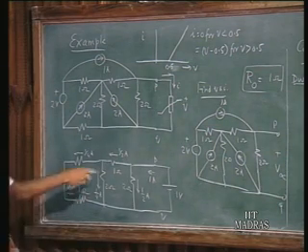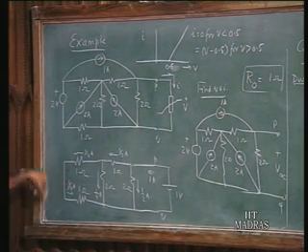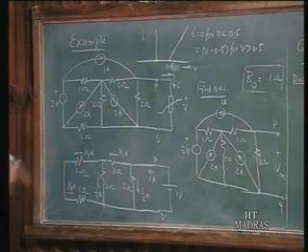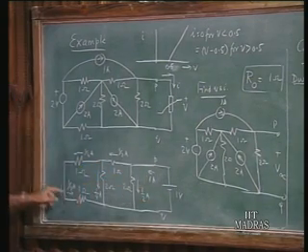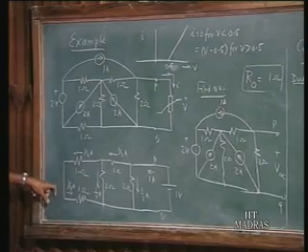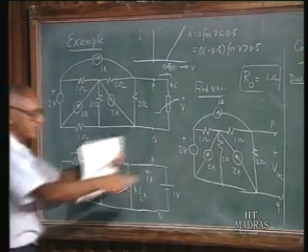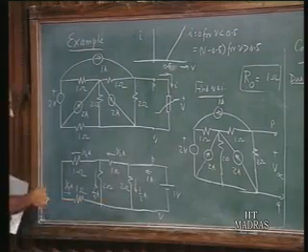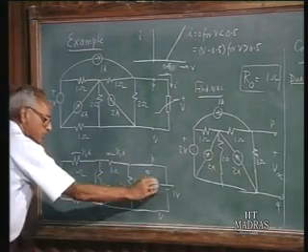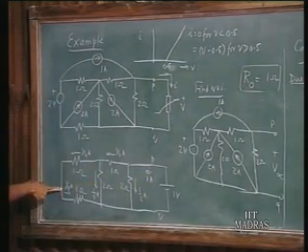But we observe here that in this circuit, once everything is deactivated, suppose we are exciting this by a current source of 1 ampere, the current here is 1/4 of an ampere. The original network is when the source is removed, that means this is short circuited. You are introducing a 1 ampere current source and you are measuring the current here is 1/4.